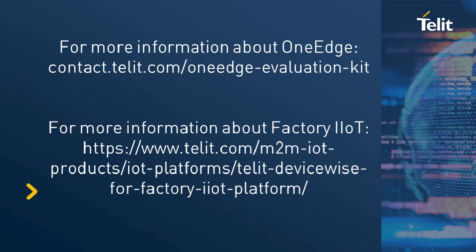Very good question on eDRX. So does your stack support eDRX for a more reactive network to device control? And the answer is yes. This has been one of the areas where we really believe we're strong. Yes, I can take a Raspberry Pi, I can put a lightweight M2M stack on it, I can connect it to a modem from any vendor and get connected. But when you're doing that, you have very little control over the details of exactly how the modem is operating and behaving.